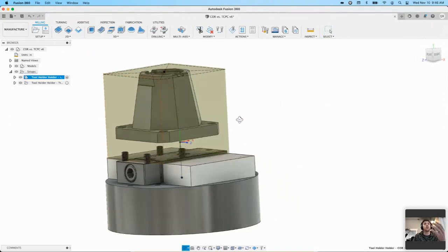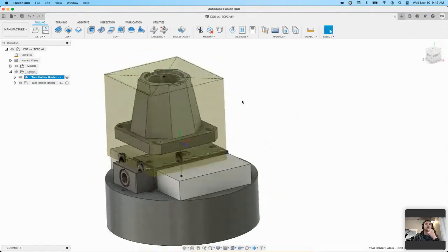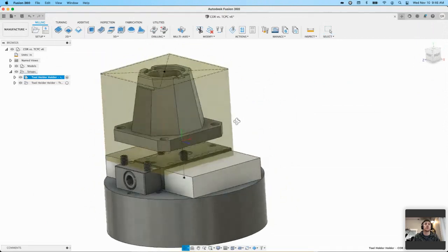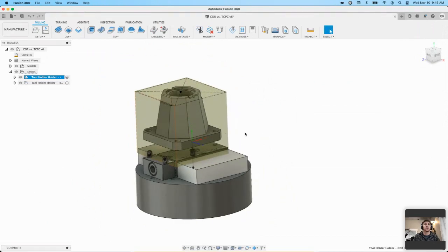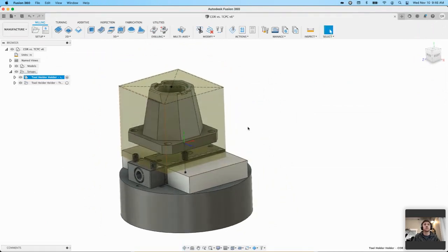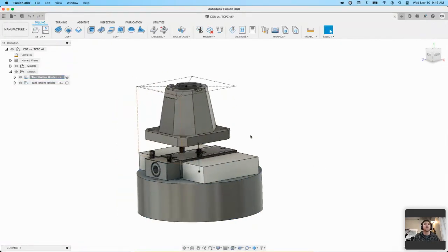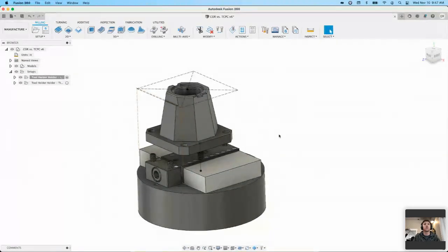The reason we had to use that point is so that in any position that the machine might be in, the machine knew how far to move from that point to make the correct moves to make cuts on your part. This worked well. It allowed us to provide a 5-axis machine and perform 5-axis moves, but there were some downsides to it. Basically, with this point being a floating point in space above the B table, which is represented here, we had to make sure that our part, as represented by this part here, and our stock were accurately positioned relative to that point.